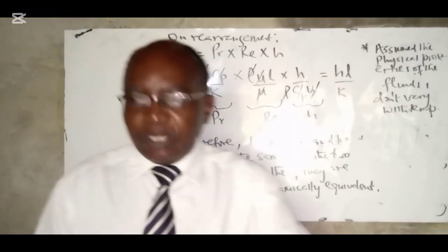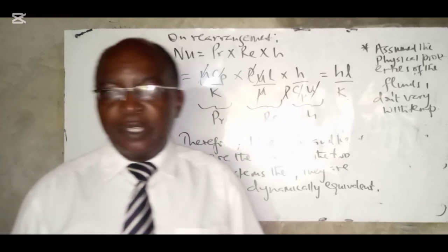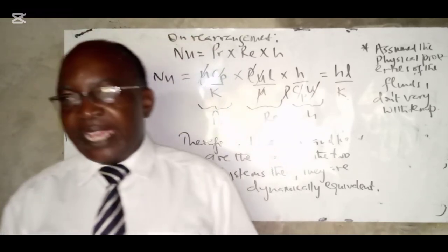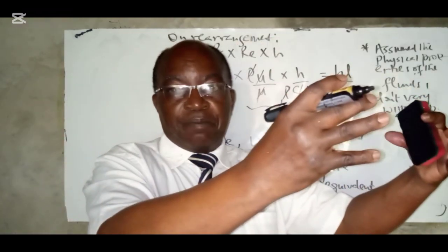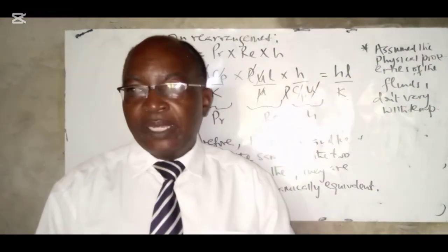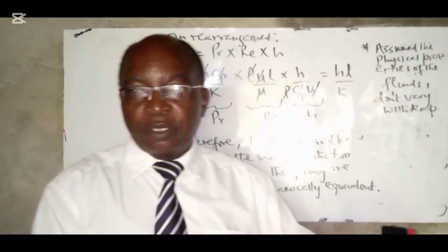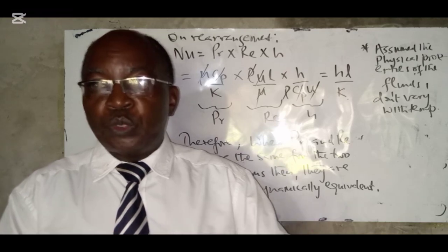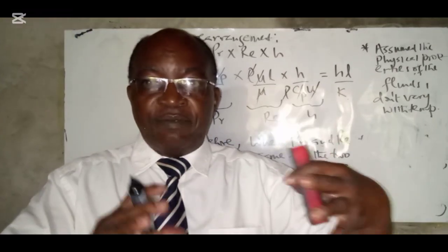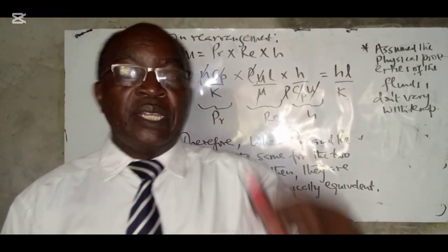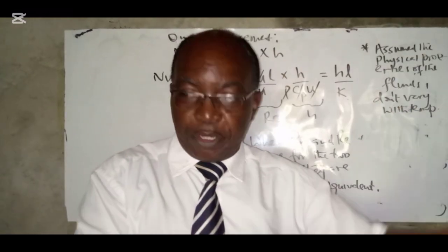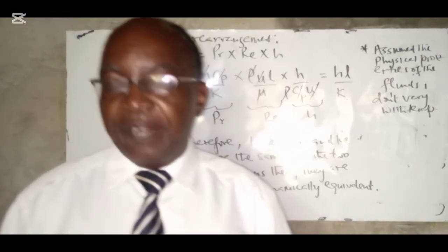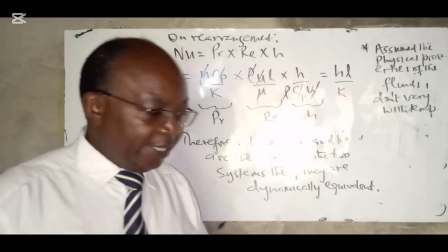So, when two systems are dynamically equivalent, it can help you design that other bigger system, which probably you want to work as you're designing it with small models, small prototypes, which you will actually use to transpose the information you've gotten here to compute data involving the bigger models. So dynamic similarity is a very important principle in design.